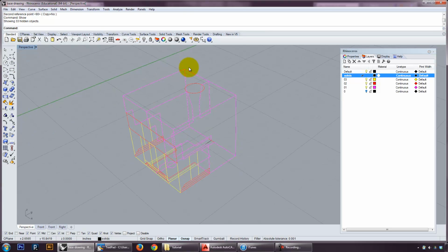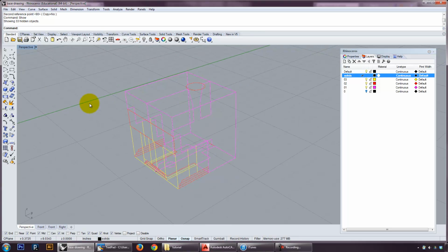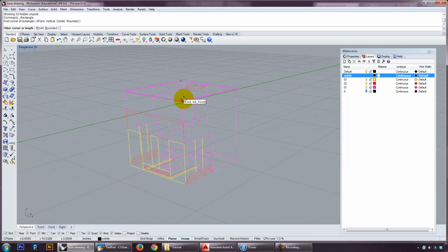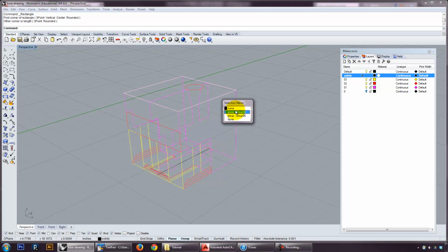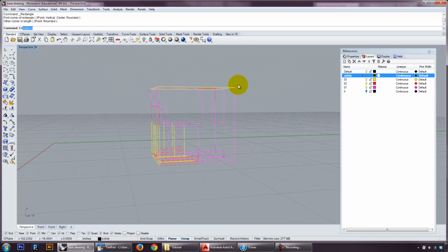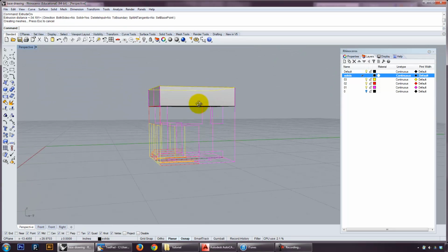So I typically don't extrude directly from the lines that I generated. Because in many cases they didn't come in very well from CAD. I might have done a lot of trims and things, and so they're not joined lines, they're maybe multiple overlapping lines. So to maintain precision, particularly in a simple model like this, I use the scaffold literally as a frame, and on my layer I'm going to go ahead and draw the line I want, which is actually this roof line. And you can kind of see that here. Okay. And then I'm going to go ahead and start by extruding it, extrude curve, down and snapping here. So I get this chunk that I have.